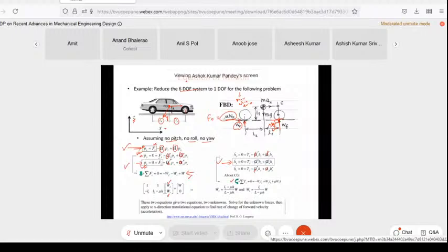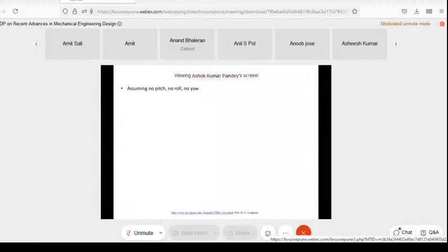So because all other components are now computed, WF is computed, WR is computed. To find Fx, you simply have to do mu times WR. Since WR is computed, you can substitute it over here. That will give you Fx, and then Fx is equal to max or m x double dot, right? And then you can integrate it to find out acceleration, or velocity or displacement, whatever you want. So that's how basically we try to do it.